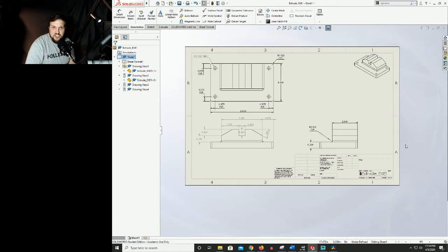When we make changes to a drawing, it's called an engineering change. We've got three different ones: a request, an order, and a notice. But when we do these, we have to have a way to identify where on the sheet that change has actually taken place. That can be anything from a dimension, a hole size, a material. All of those can be engineering changes. And each one of those is marked with a letter.